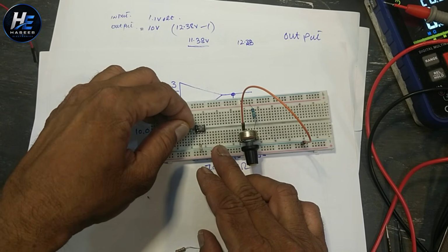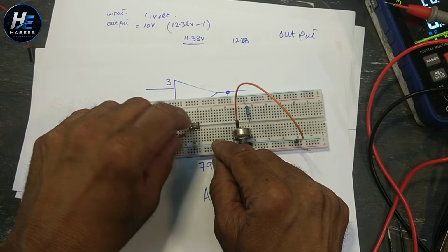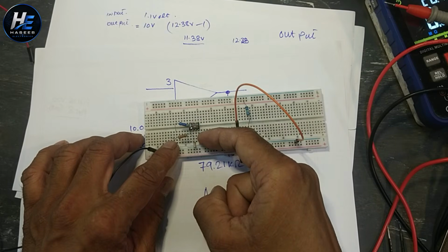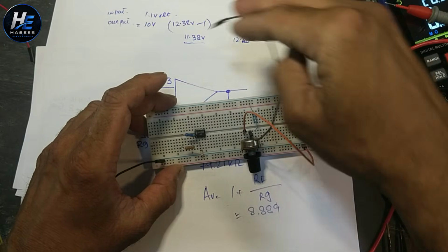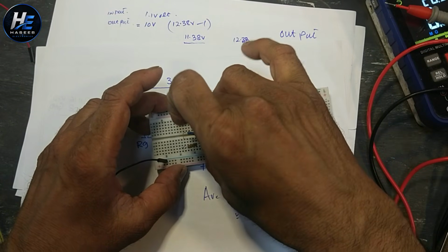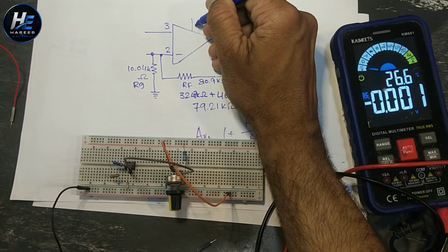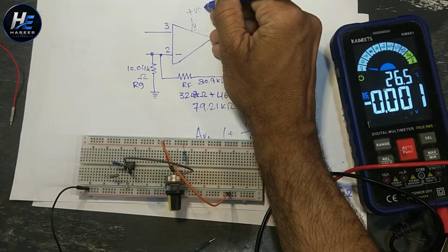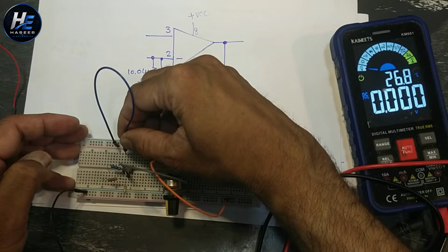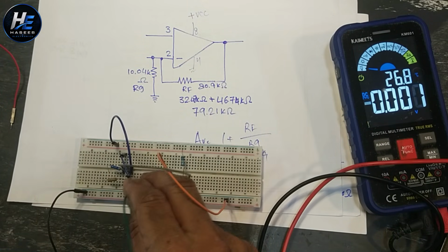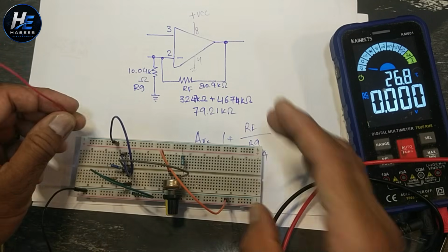47 kilo ohm at pin number 1 and series resistor 33 kilo ohm, now one resistor. Now we will inject potentiometer signal to pin number 3. Now we will connect pin number 8 positive VCC, pin number 4 ground. This is our power rail. Now we will apply power.